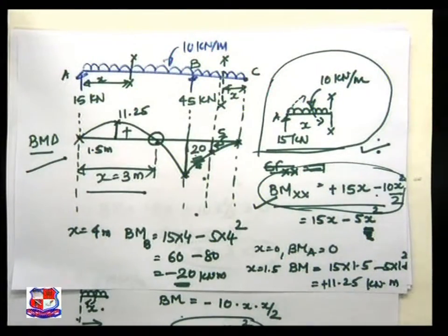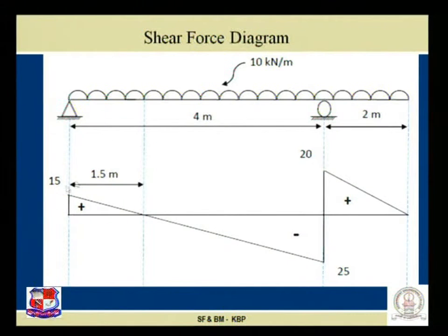So now I think you will understand very well how to find the bending moment diagram. Please see this particular PPT. This is the shear force diagram. X is equal to 1.5 meter, where shear force is 0. Extremely sorry. There is a reaction over here, and we can observe a sudden change in the shear force diagram. So if we revise the basic concepts: first, at the section at which a point load is acting, the shear force diagram changes suddenly. Second, for a UDL, the shear force diagram variation is given by an inclined straight line.